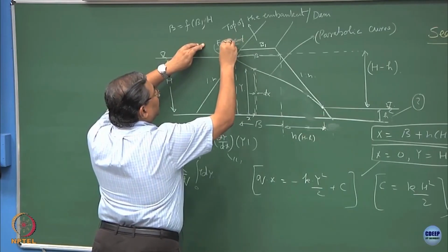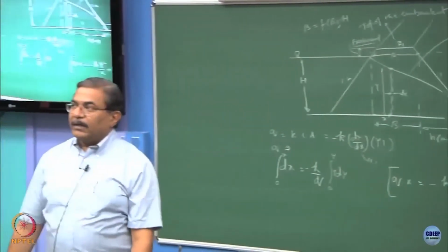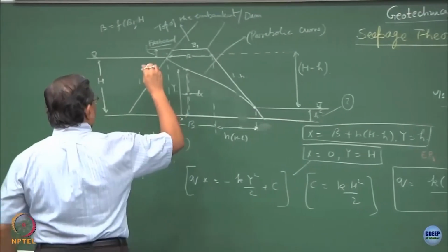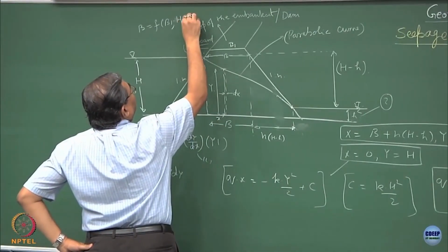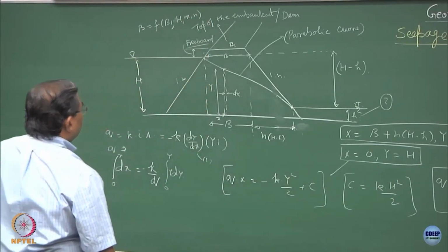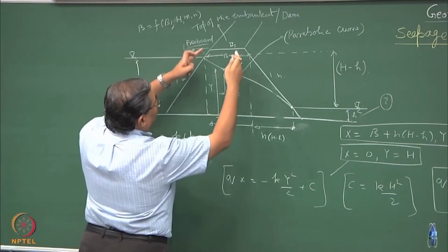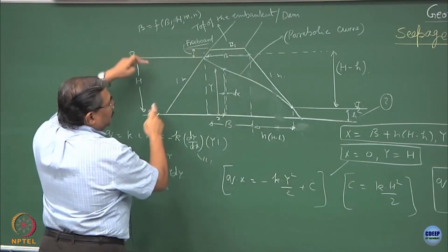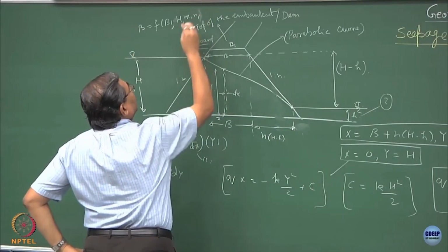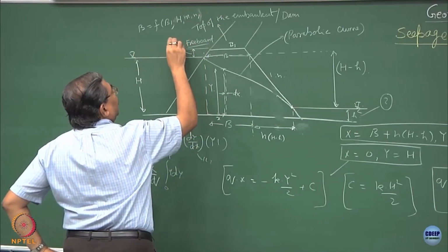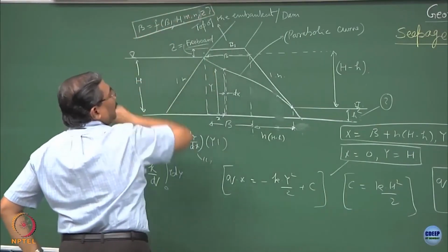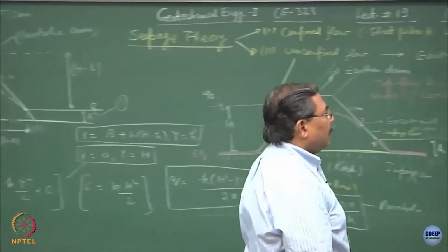You must have been reading in newspapers why freeboard is so important and why the cities are getting drowned these days. There are so many cases including Maharashtra and so on, is it not? M, N. So, I can design the top width keeping in view the H, the two types of slopes, how much water is to be retained, what is the freeboard. So, I will include in this the freeboard, let us say as Z. So, this becomes a typical cross section of the earthen dam,